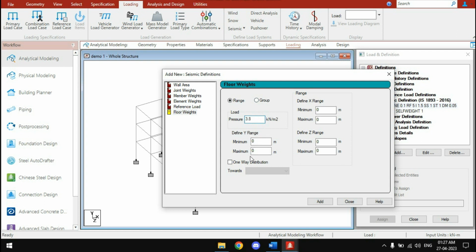And these are the ranges which have been defined by the structure wizard, as we discussed earlier while making the model. As our building is G+2, and I have defined our Y part around 10.5, I'm adding 10.51 just for the calculation point of view, nothing else.